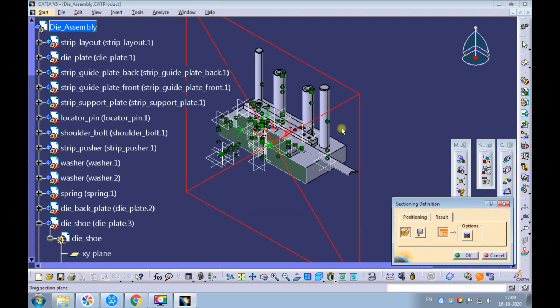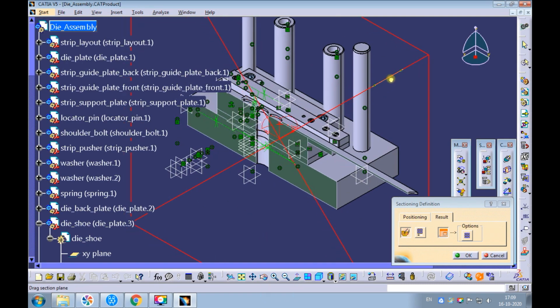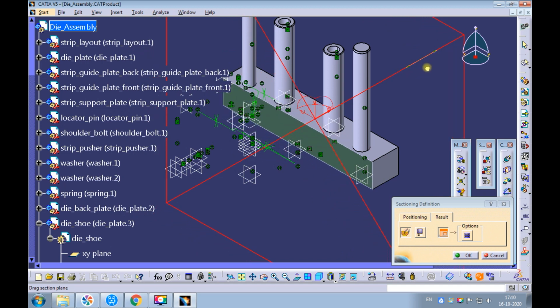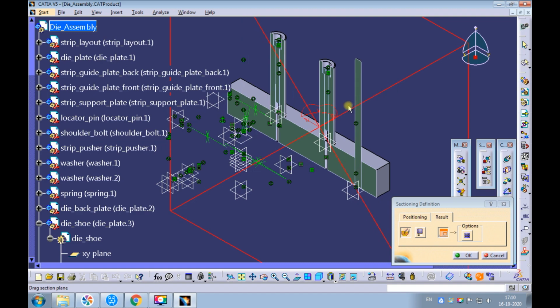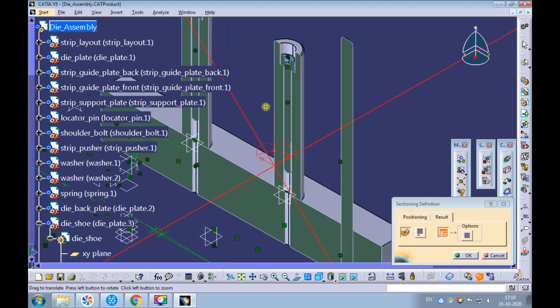Pick volume cut on the Result tab. Observe the assembly of the stroke end blocks and the screws. Observe, we have made a mistake in calculating the depth of the counterbore.